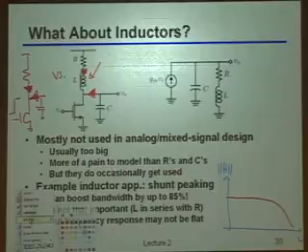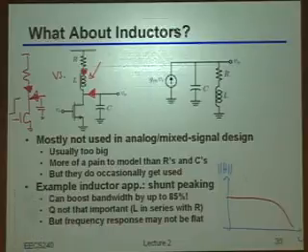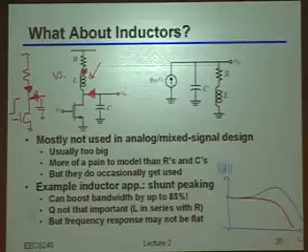If you compared that against the shunt peak design, that will typically look something like this. Okay, so it won't really be flat. That, again, has other implications in terms of the performance or behavior of the rest of the system. Okay? But nonetheless, it's a good thing to have in the back of your head because there are some applications where you may want to play these tricks just to get that last 50, 60% of bandwidth improvement.